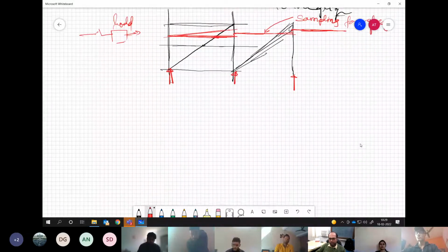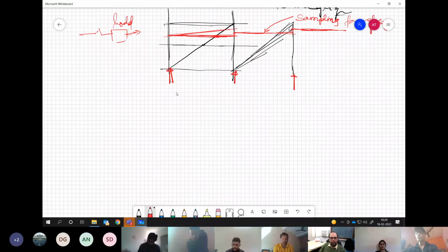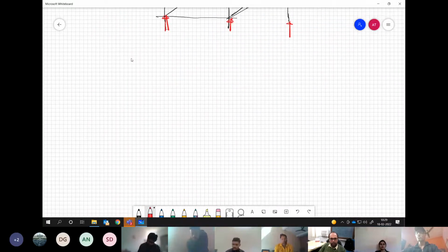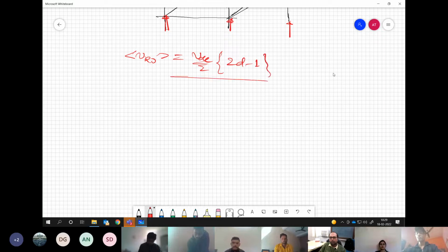Now, when we have said this, what we are trying to do basically is relate our output voltage, which we have derived in terms of the duty ratio, with the control variable or the reference M. Now when we are saying that M is some sinusoidal quantity, we can write M in this form. Correct?